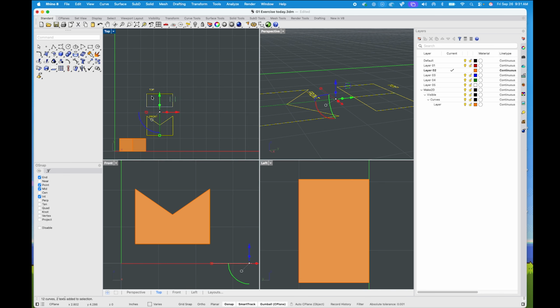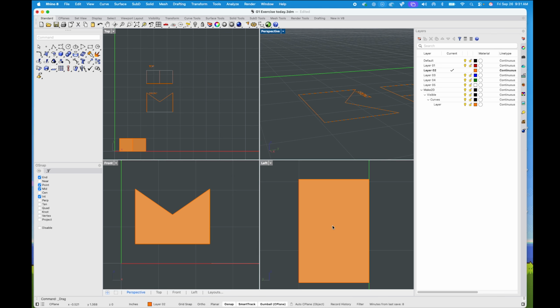I could take all of it and move it up a little bit, especially if it's in the way. But I want to rebuild that last move. I want to get that side view. So again, let's make 2D. Let's definitely make sure our hidden lines are there. We'll hit OK. And there it is, right there. And it even gets that little hidden line for us, even though it is a microscopic hidden line.